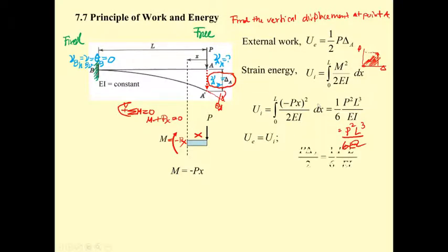You have this equation. By doing this equation, you can just manipulate what we have. We have P, right? The P, test the P out. That P squared is going to be P, and this one cancels. This one is going to change to 3. So this one is going to have the equation for the deflection as delta equals PL cubed over 3EI.